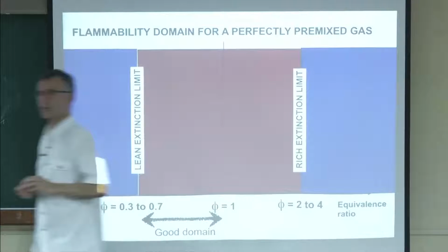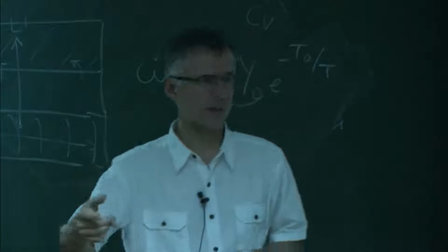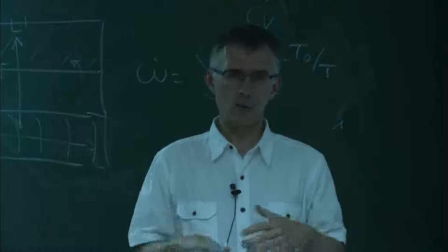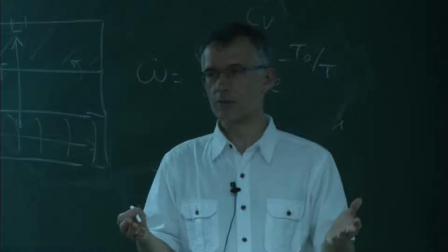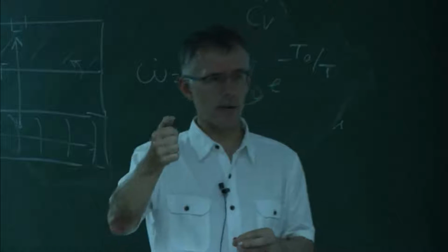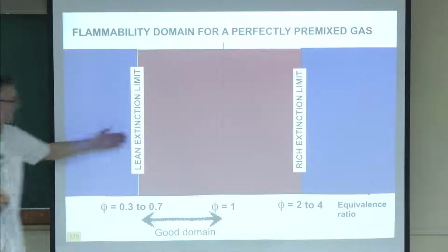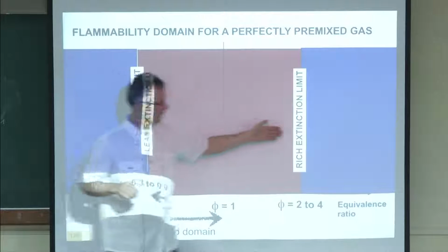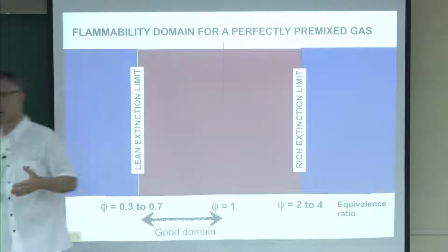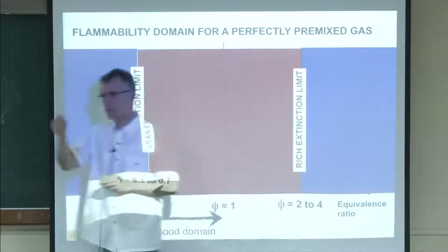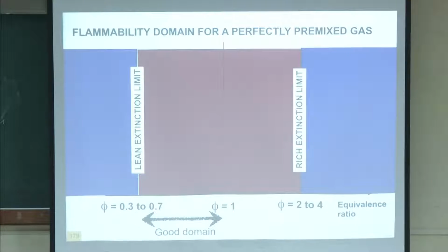Which is a surprising point too. If you have a gas leak in this room, and I suppose I can mix everything with the air, for the first few minutes it will not be dangerous because it will be on this side. So you can have a leak of methane and click your lighter and it's not dangerous. Then, if there is enough gas at some point, you should stop doing that. But if you wait long enough, and you have now too much fuel in this room, you won't be able to ignite it. If the mean equivalence ratio is 4 or 5, you will try to ignite it, and it won't start. Okay. I won't go into the details. There's a small detail here.